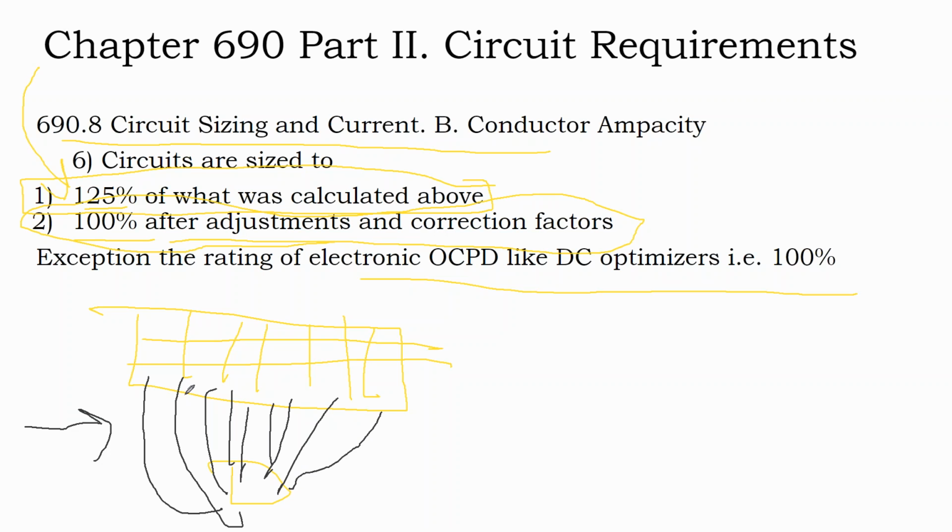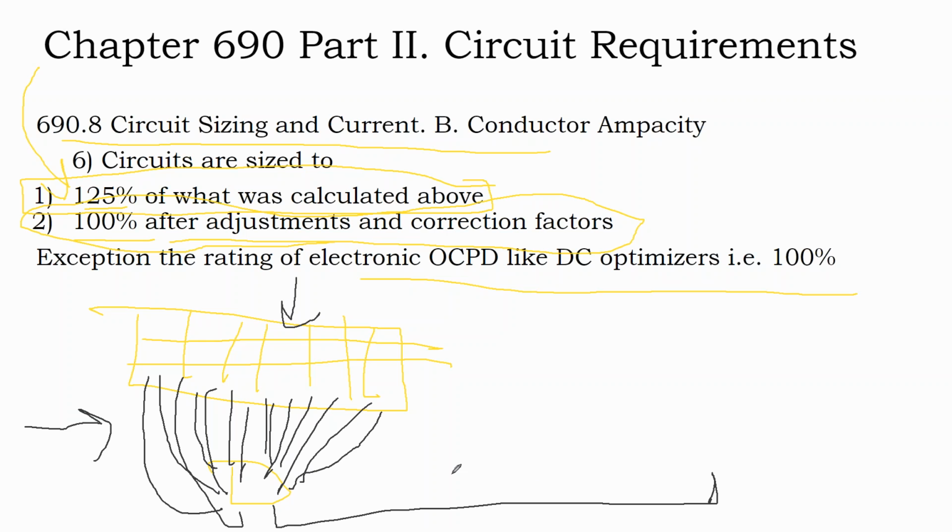But on a commercial array where you just have tons and tons of solar circuits, you might use a combiner box and have a lot of circuits in and one circuit out. At least that's how old school solar used to be. And in this kind of old school configuration, all of these conductors were uncontrolled. Nowadays we have little boxes behind every solar panel, and so these conductors are controlled.